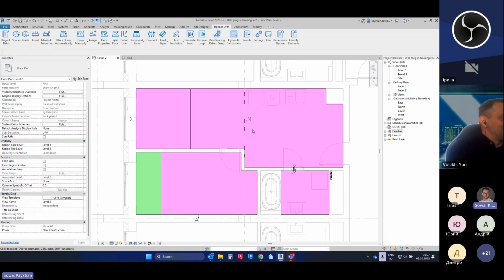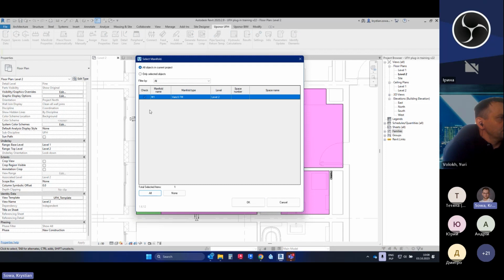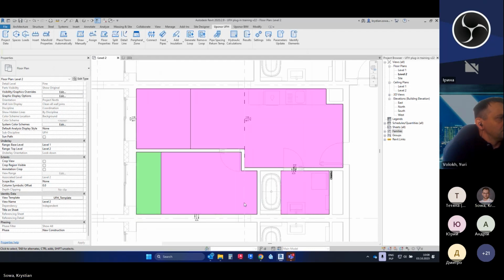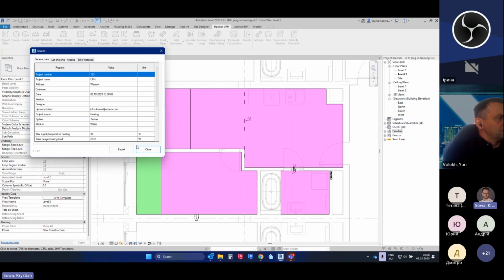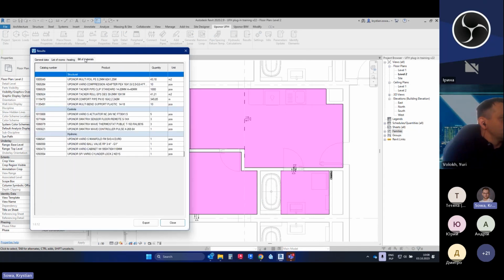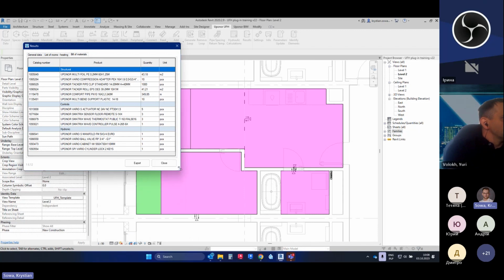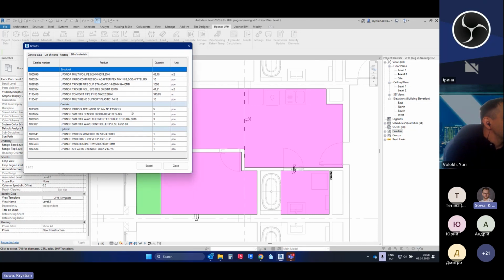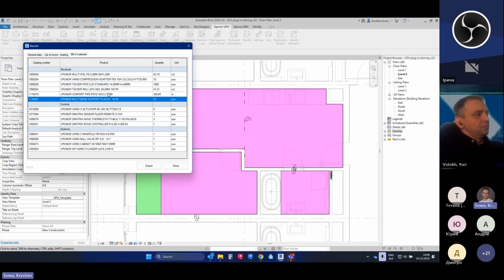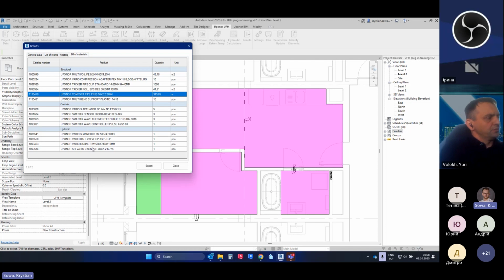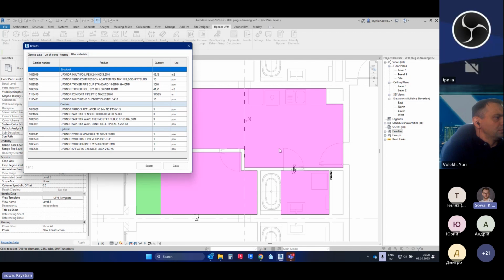Okay. Then we'll close this, and I will also show you that here in the results, so next to the hydraulic calculation, we have the results icon. Also, we need to select the manifold and click OK. I just want to show you that already we also have the bill of material here. So the full bill of material, as you see, without drawing any pipes, we also have the full bill of material with all of the elements needed for the installation. Also with the pipe length and everything, with the room control system, everything already here is in place. So as you see, not only calculations are available without the pipes, also the full bill of material.